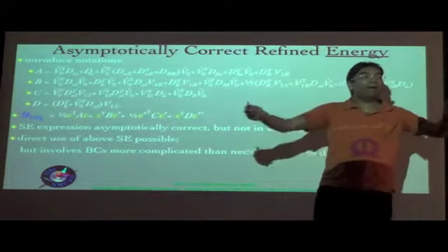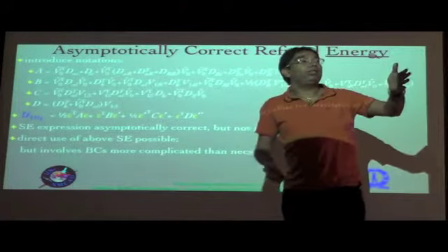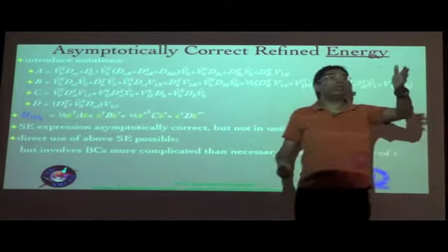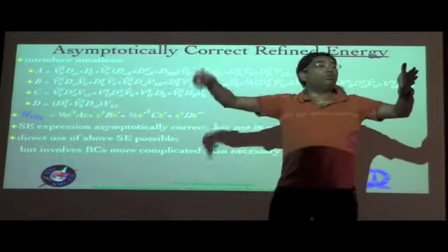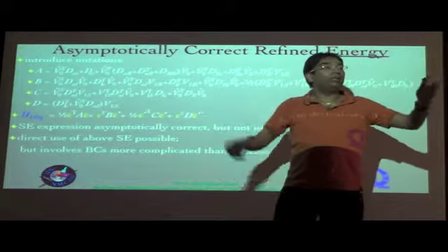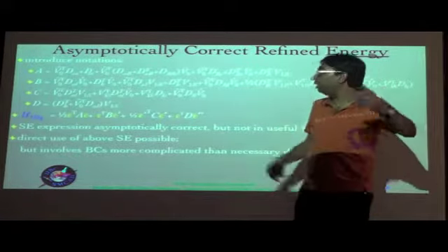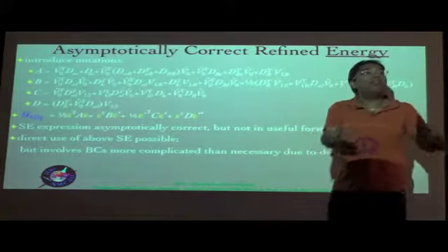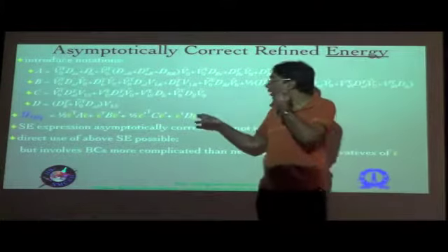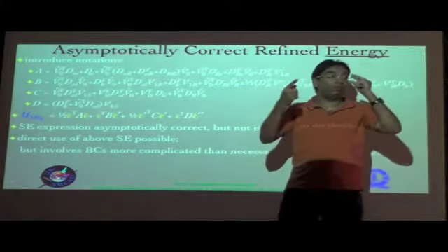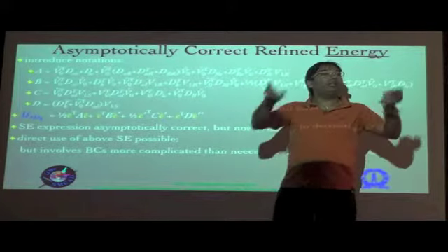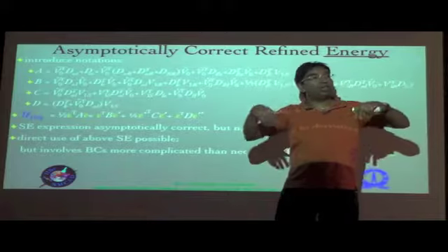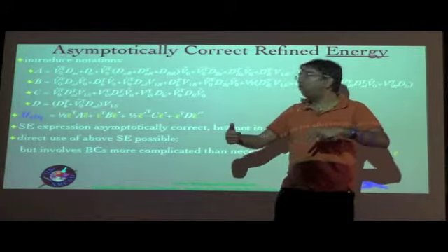For example, if you take a cantilever beam, you typically talk about, let's say, just the displacement and rotation at one of the ends equal to 0, and then you know the force or moment at the other end, and basically you evaluate things related to that. In this case, you can have additional boundary conditions which are required because of these prime quantities, because remember, the governing differential equations will be derived by minimizing the total potential or using Hamilton's principle, later we will see.